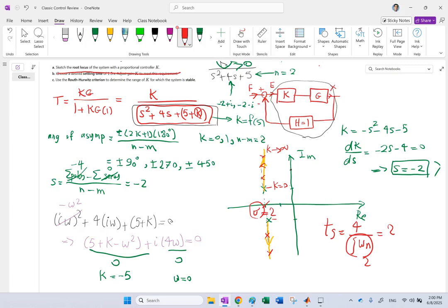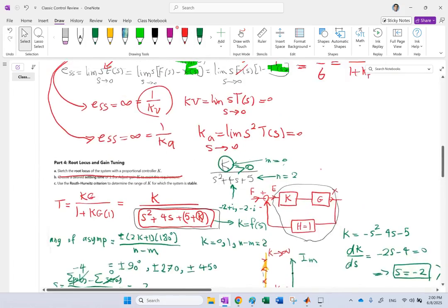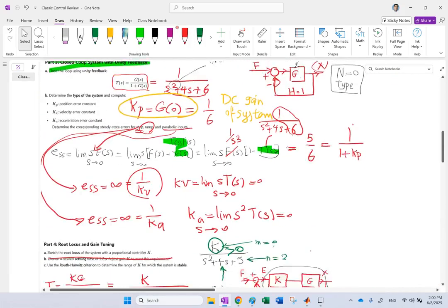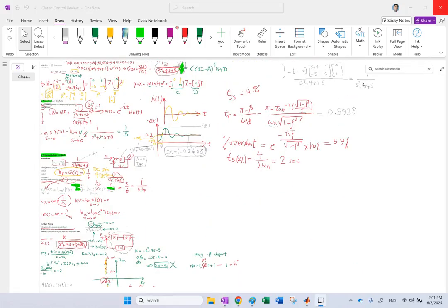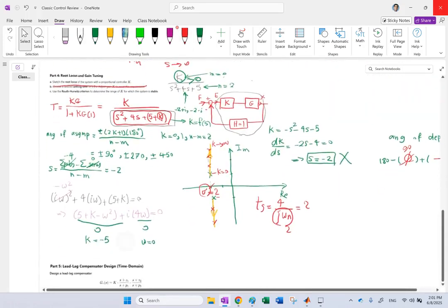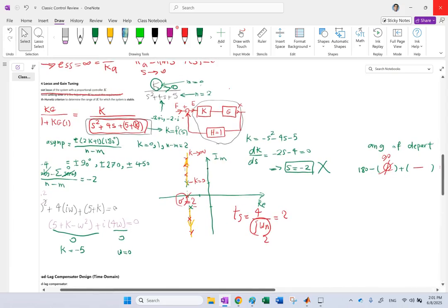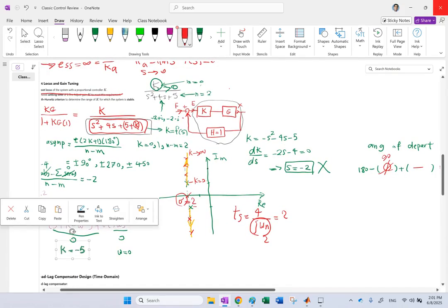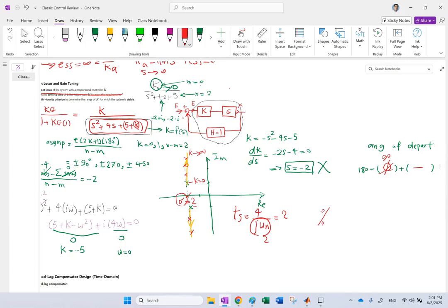But you might pick gain k to achieve something else. For instance, in this system, if you remember, the overshoot percentage, let me find it, it was basically 5.9%, or the rise time was about 0.6 seconds. Can I change those by changing gain? The answer is yes, you can. So remember, the percent overshoot of the system is a function of the damping ratio only. Correct?